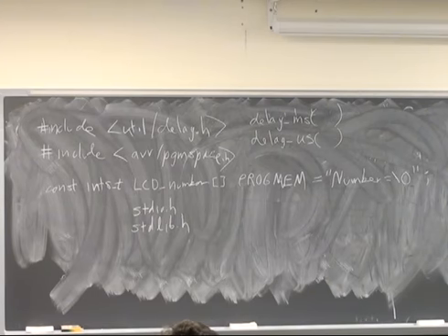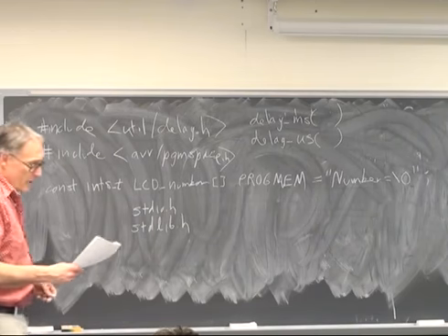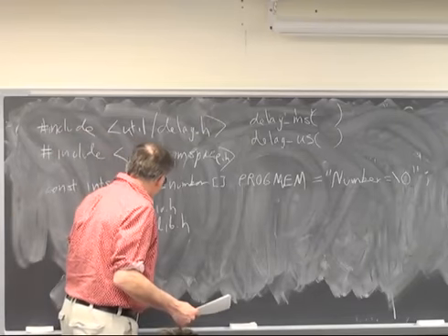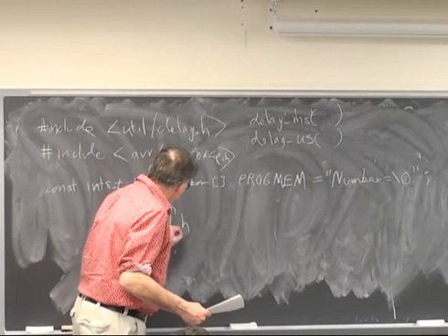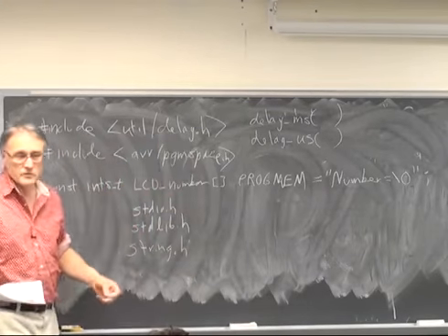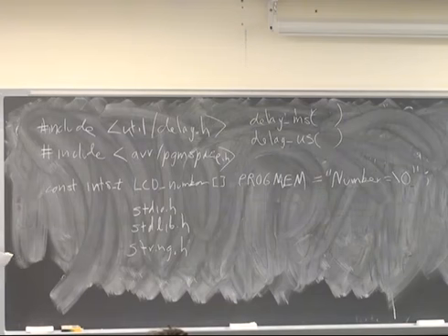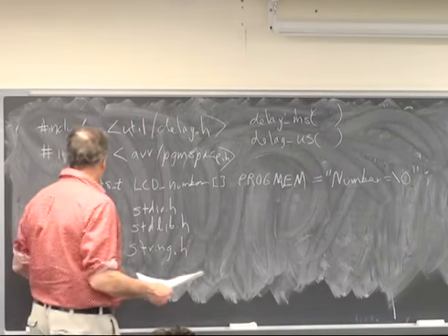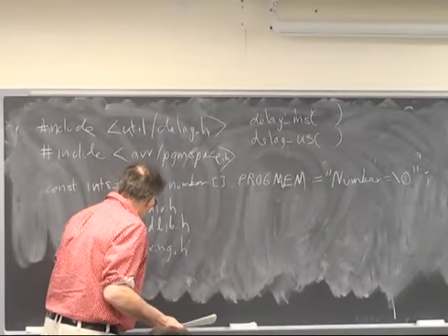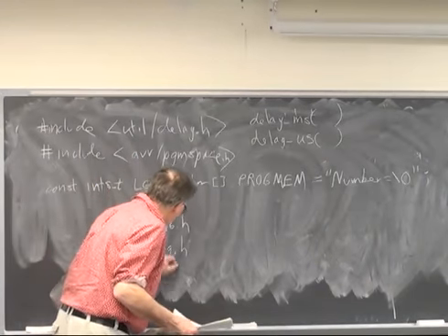There's a link on the Lab 1 page to the WinAVR GCC AVR Lib, which has all of these functions laid out for you. We're going to include string.h. You can guess what that is. It's string functions of various sorts. And we need to include LCD lib.